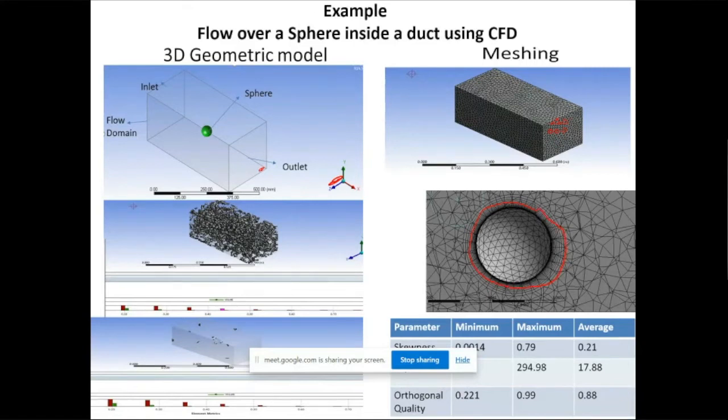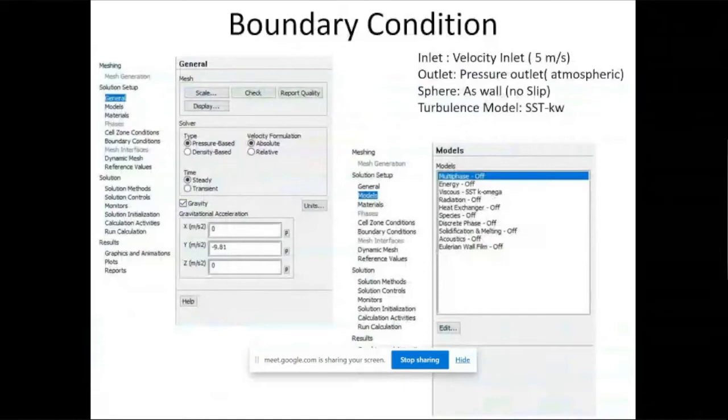we have applied the boundary layers. Here you see, these are the boundary layers. These we have to make once we are applying the fluid flow equations. Once you do this, now we apply the boundary conditions. Suppose whether you are going for the gravity effect or not, then we can select some kind of turbulence model here, SST k-omega, some viscous model.